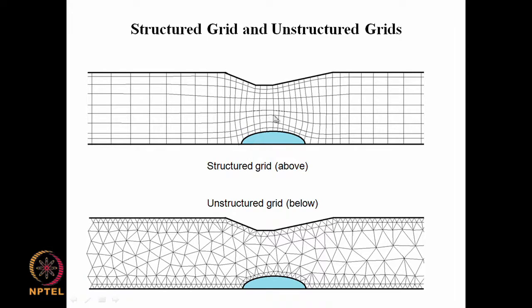So it is possible to use curvilinear coordinate lines and come up with a structured grid where the grid points are at the intersection of these curvilinear coordinate lines. This particular coordinate line is curving over this part, and then after it goes up here it is almost straight, and this line is curved like this, but far away from it, it is straight.